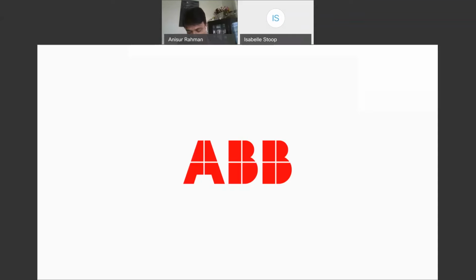How can we integrate with the existing Nickel West substation already in operation without having a shutdown? Yes, if it is ABB, I'm thinking it is all our ABB Relion relays with IEC 61850 9-2. Now, if it is there, then you don't need to do anything. You just have to configure that and it will be done by itself.